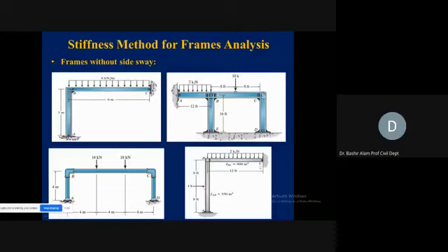But if you see at joint C, here we have a hinge support, which can take the horizontal load and will not allow the lateral displacement. So that is why, looking at support conditions, we declare this frame as a non-sway frame, or without side sway frame. Although it has the lateral force, C can take it, and A can also take the horizontal forces. So we declare this as a without side sway frame.